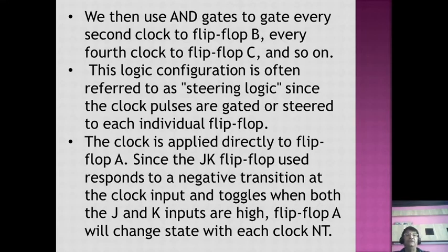That means this parallel counter we designate as a steering logic parallel counter, because the clock pulses are steered to each flip-flop according to its requirement. Every second clock pulse is steered to flip-flop B, every 4th clock pulse is steered to flip-flop C. The clock is applied directly to flip-flop A.